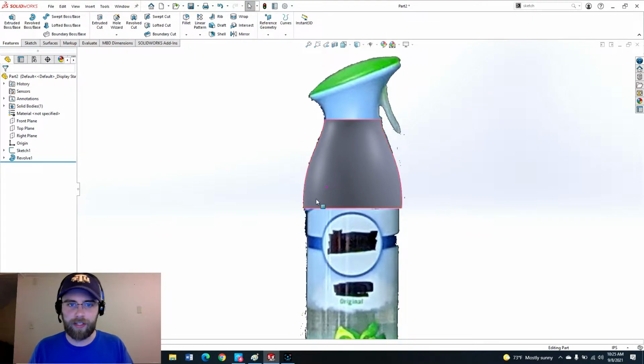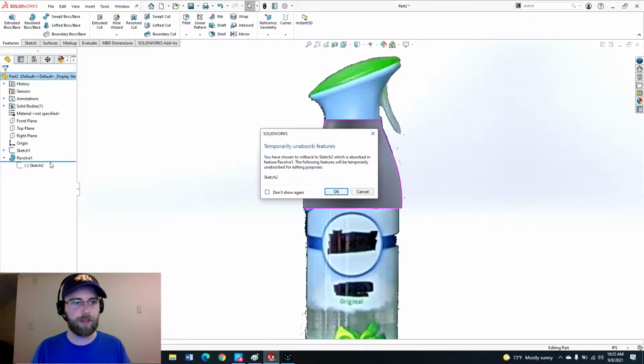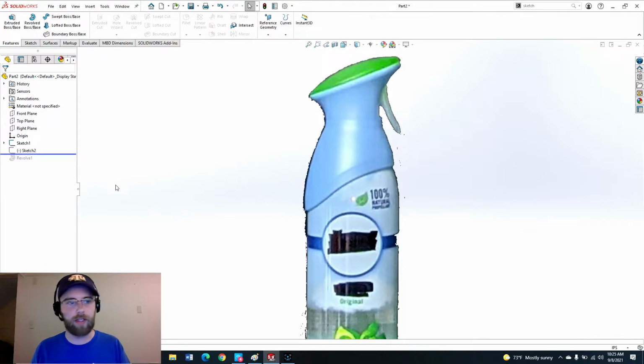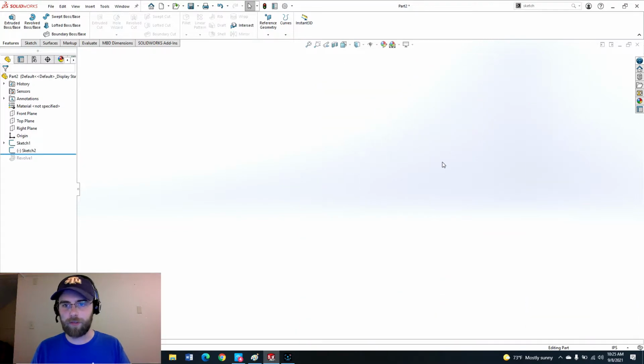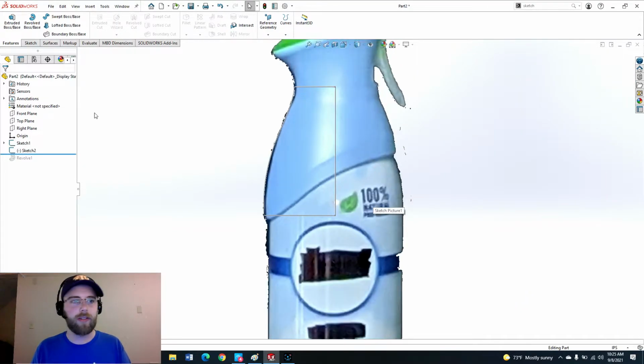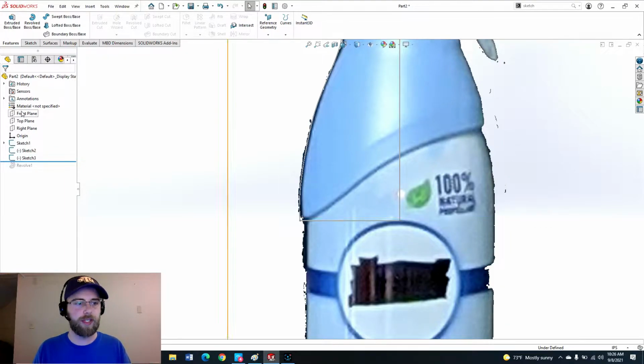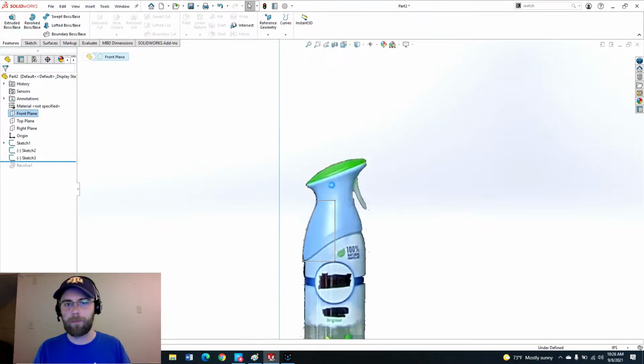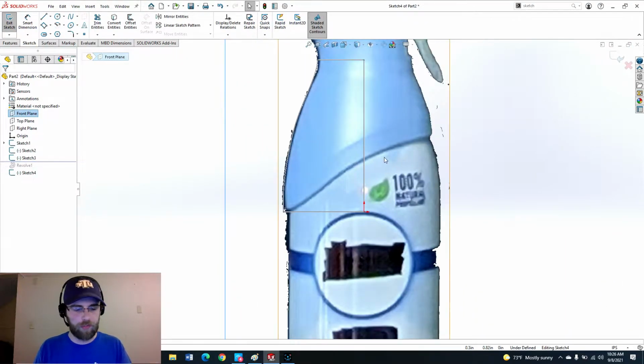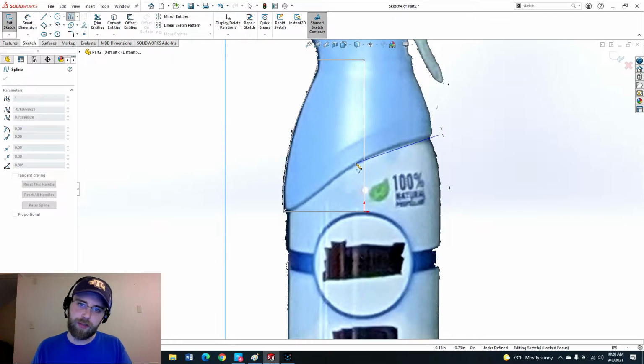And we can go ahead and cut in that little swoop that goes in there. So to do that, let's go back in history, bring up the blue bar over here in the tree to before we revolved. And let's make another sketch to draw out that feature. There we go. So let's go ahead and draw in that little swoop. So that's another sketch on the front plane. Looks like more spline work, so put in a spline here. And we'll do another 3-point spline.